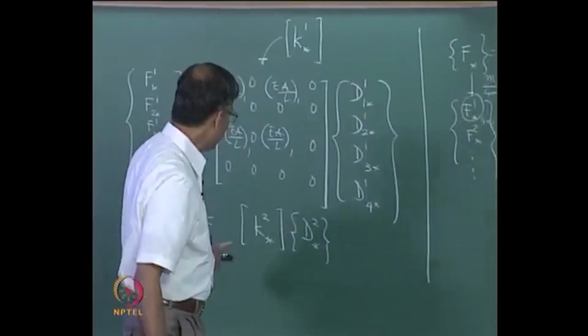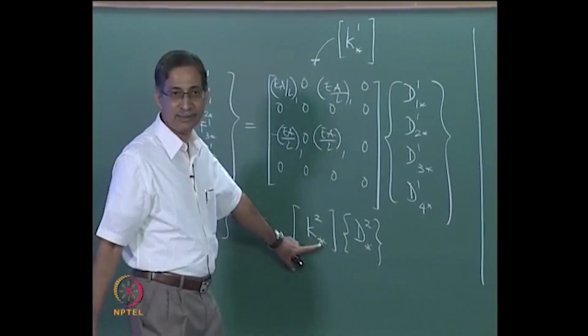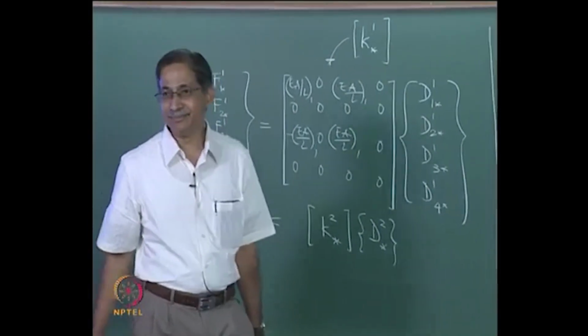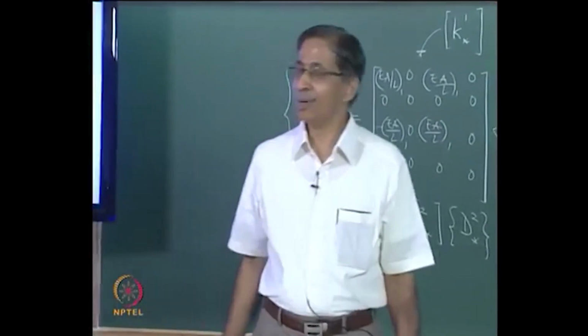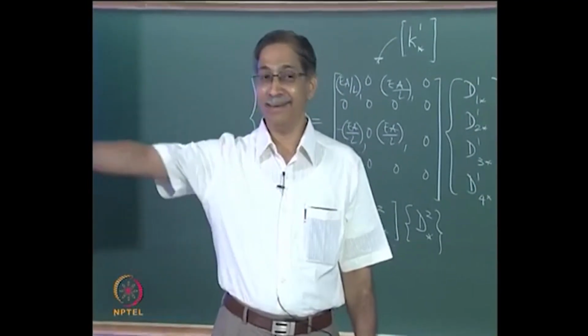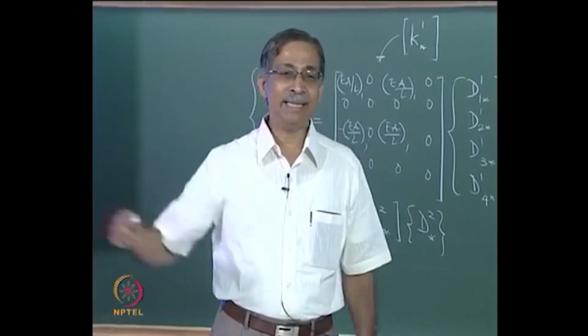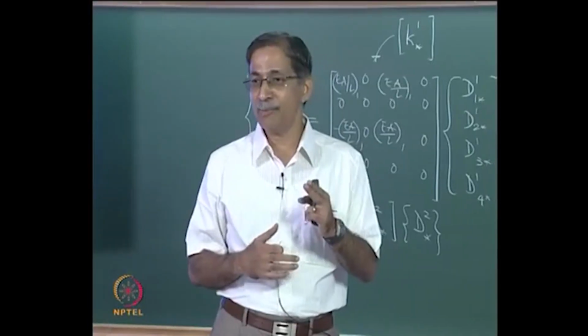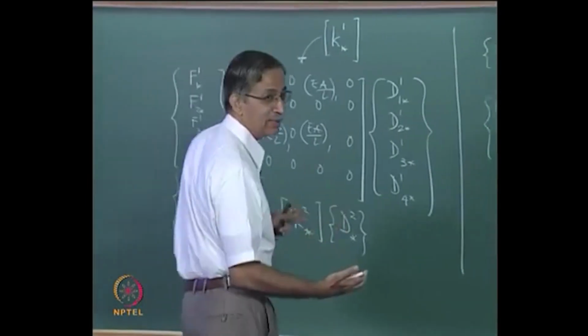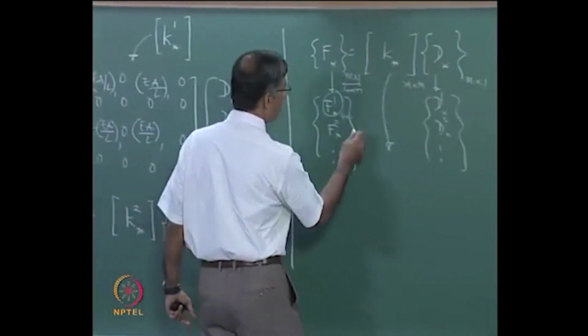You've got all the individual element matrices. How will you arrange this? Put all these next to each other. No? So K1 star, K2 star, diagonals. Wonderful. See, the element stiffness matrix for one element has no relationship with the element stiffness matrix for the other element. So if you really want to put in a matrix form, there's only one way you can put it.